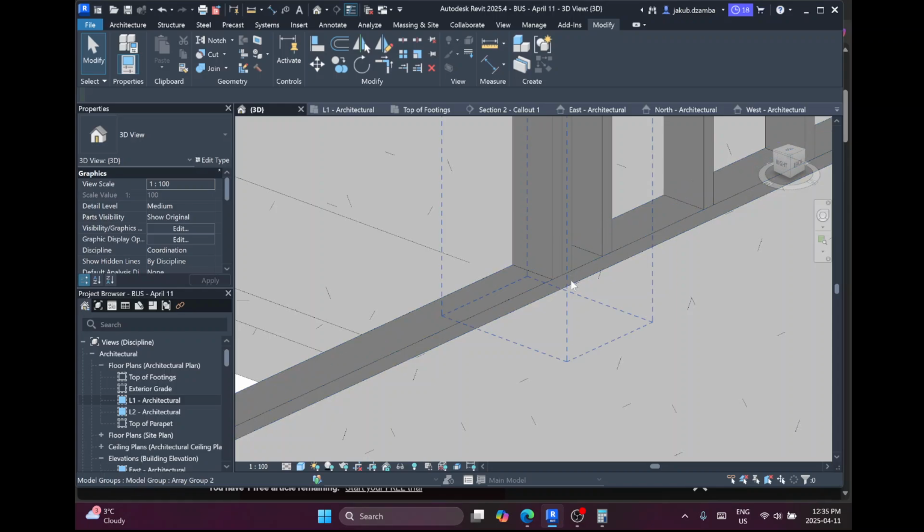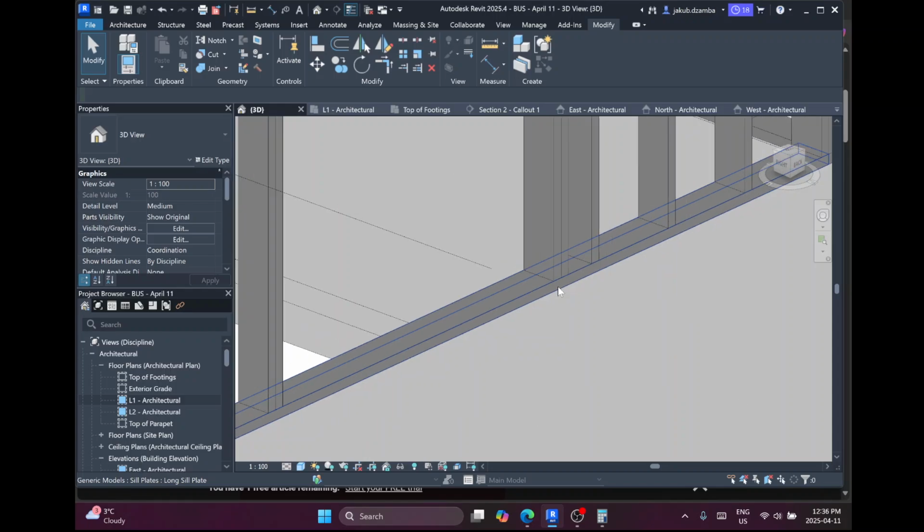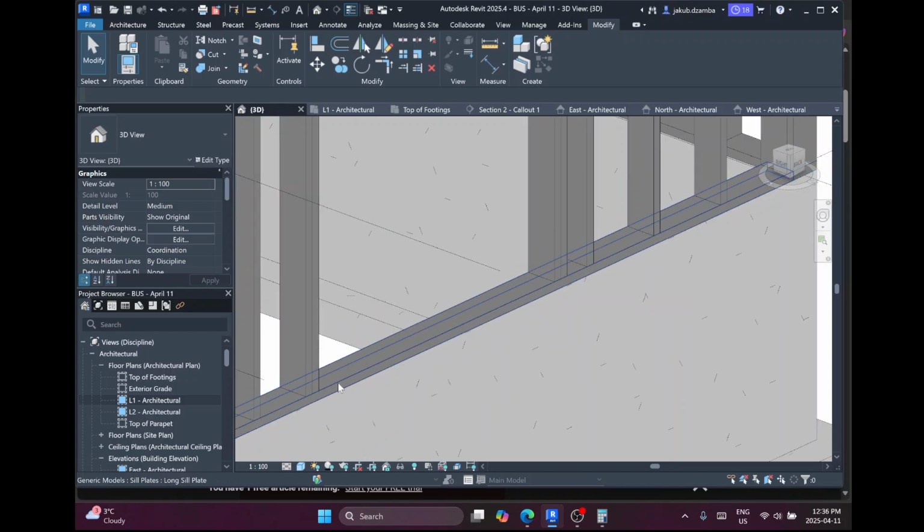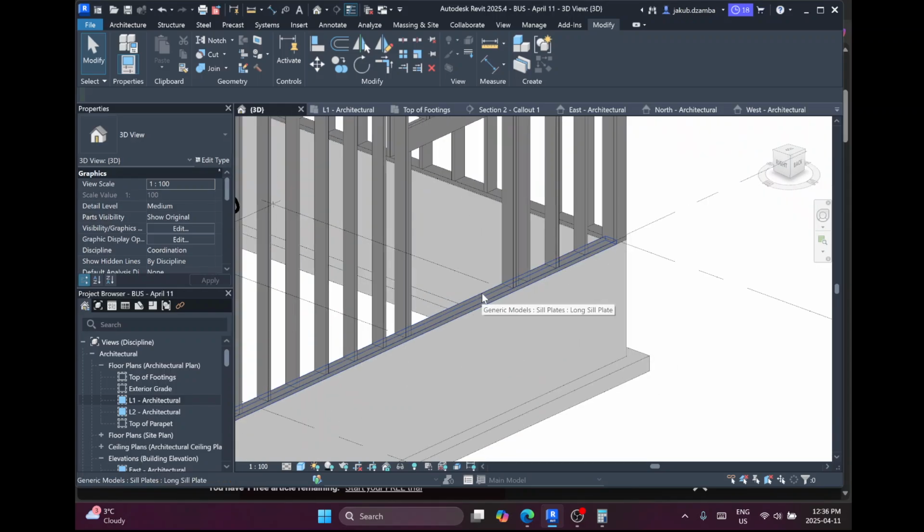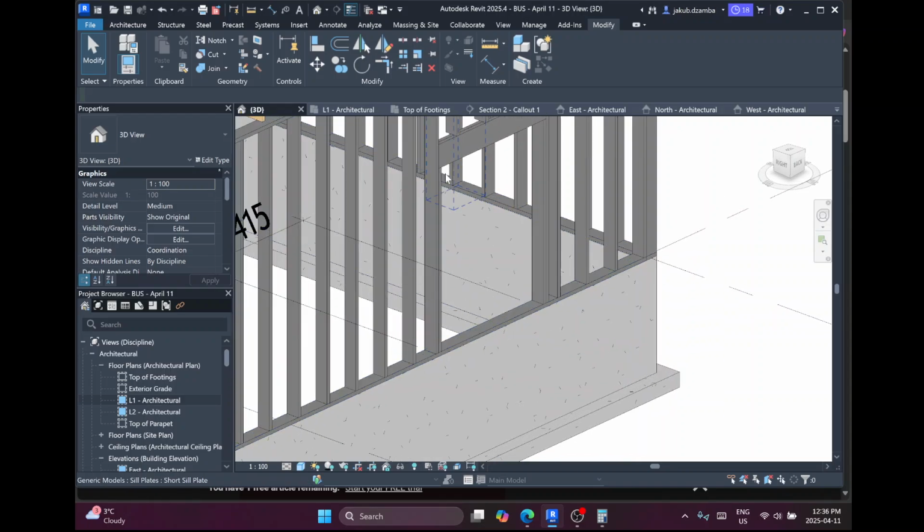And perhaps you'd cut it here, and then these two vertical studs would go to the footing, and then it would have no wood between the faces of the vertical studs. And then you would, when you're finishing the building, you just have a metal plate that spans the floor and the pavement outside. But we're using Revit in a way that isn't quite intended to be used here.